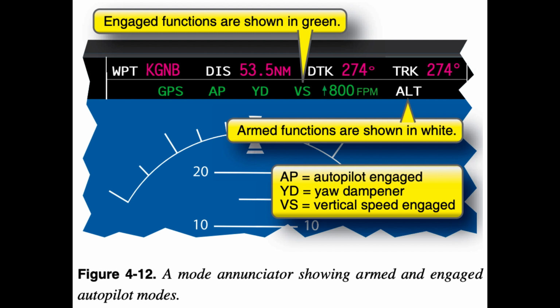You must remember that the altitude alerting system is designed as a backup, and be careful not to let the alerting system become the primary means of monitoring altitude. Most airline operators have a standard operating procedure that requires pilots to call out approaching target altitudes before the altitude alerting system gives the alert.